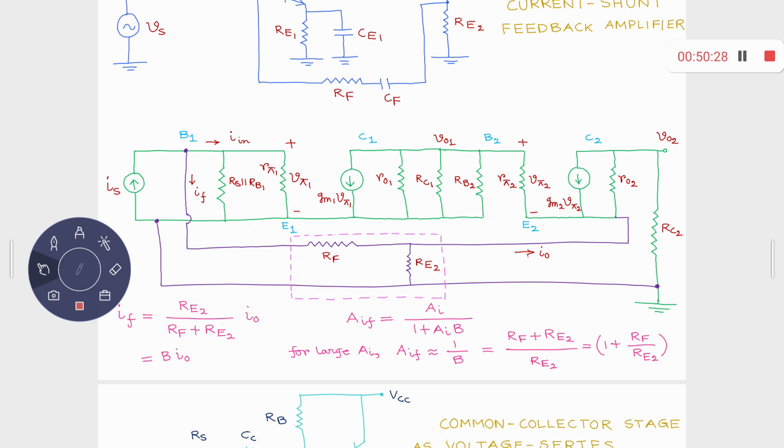These two types of expressions you have to remember while you study op amp in the next semester. One is the non-inverting voltage gain, second one is the inverting voltage gain. For the inverting voltage gain, what is the expression? Minus RF by R1. And for the non-inverting case, what is the voltage gain? 1 plus RF by R1, something like that. Right?